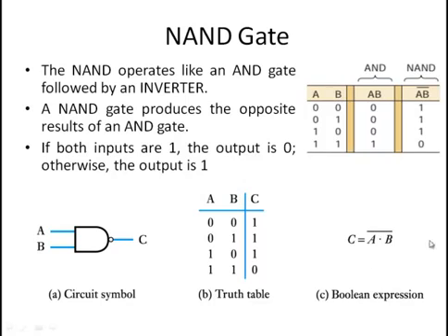expression for NAND gate. Now considering the results, if we consider only the AND, then the results will be this, but since it is a NAND gate here, we have to take the complement of all the results, and this will form the result of A.B whole bar, that is NAND, and this will make the truth table for the NAND gate.